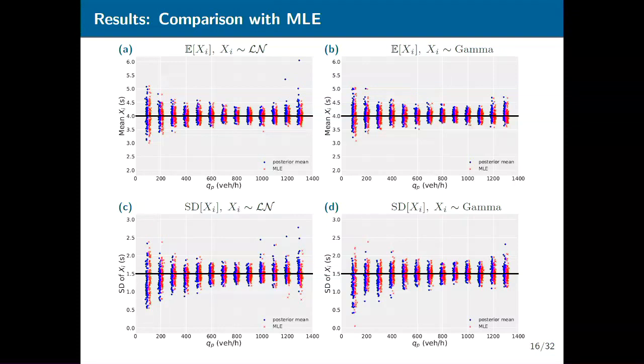Things get a bit better when the major stream flow increases and you face a bit more rejections and you can figure out where people's thresholds really are. When the flow increases so much that it becomes very hard to find a safe gap, vehicles wait on average for quite a while before entering the conflict region, and your data set simply has fewer vehicles, and your standard error increases because your sample size goes down again.